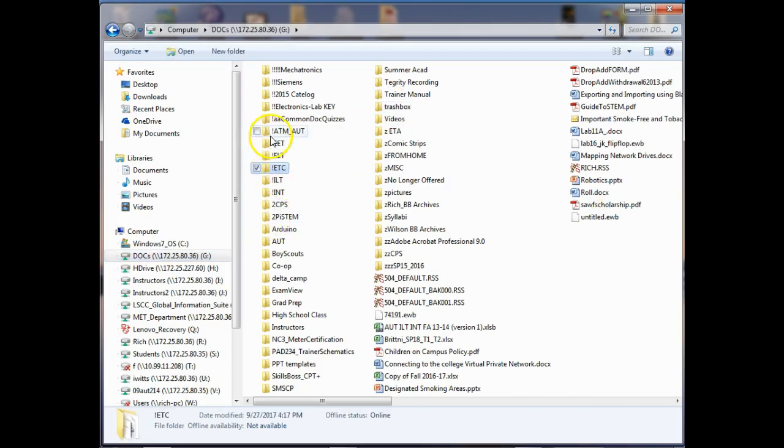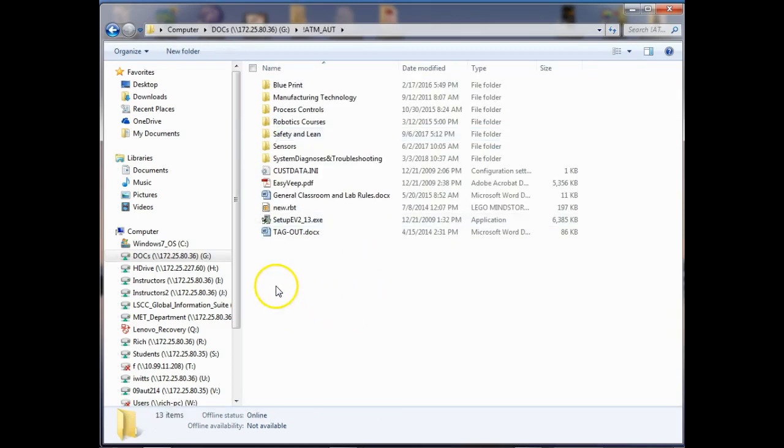Then we have what we refer to as registers. So what registers do we have available in our timers? Preset register, accumulator register, time base. And then we have a status register, or flag register.